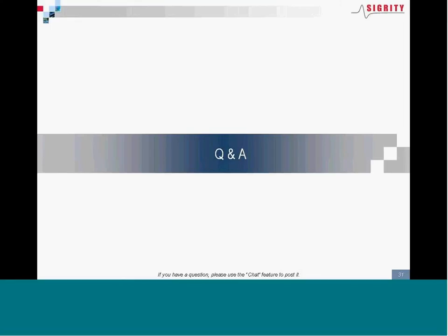I purposely did that, including the characterization step. So remember, the first time, the SPICE circuit simulator ran to generate that impulse response. In that case, that was a fairly detailed through channel topology with large S parameters that ran in about 15 seconds, I think. And then the 200,000 bit simulations ran in the order of somewhere between 5 and 10 seconds.